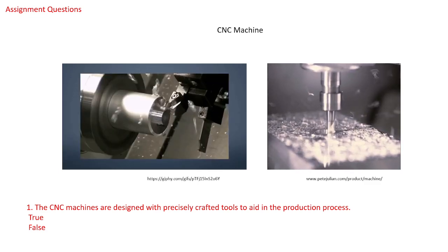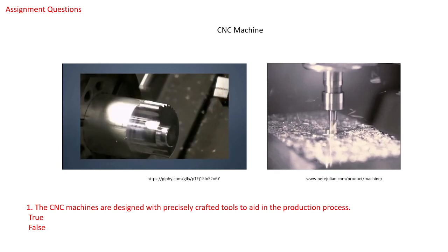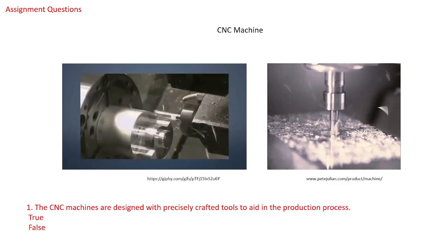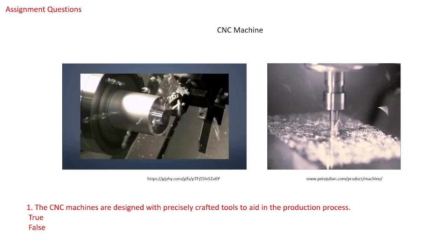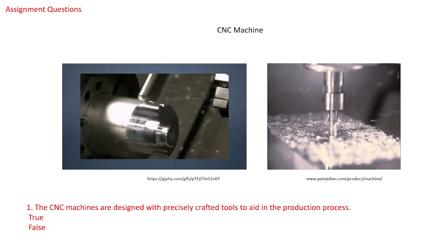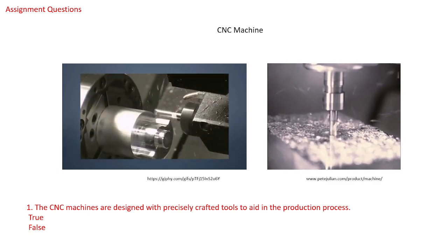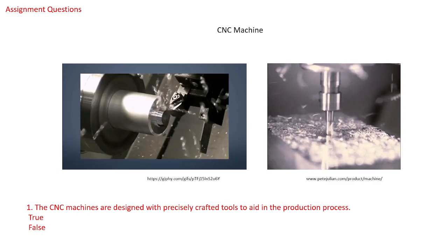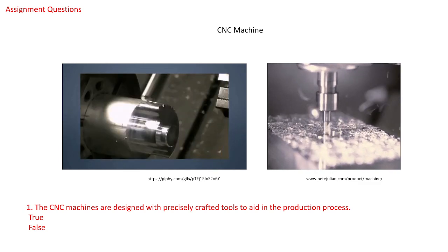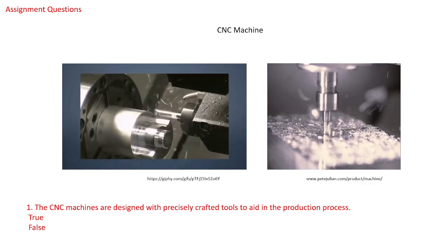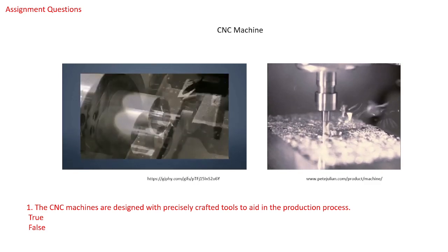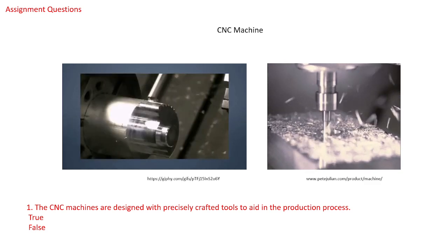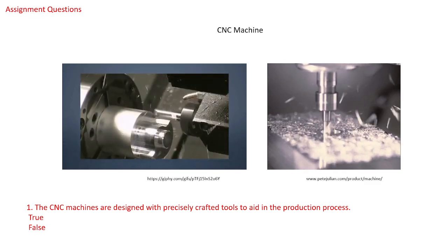So it is the setup with vertically operated spindles, which tackle workpieces from above and are performed most often on 2.5 or 3 axis machining operations. So it's basically less expensive compared to a horizontal machining center, and especially attractive to small companies nowadays. That's the way VMCs, or vertical machining centers, become more advanced, incorporating high speed spindles and incorporating that into the control programming part.